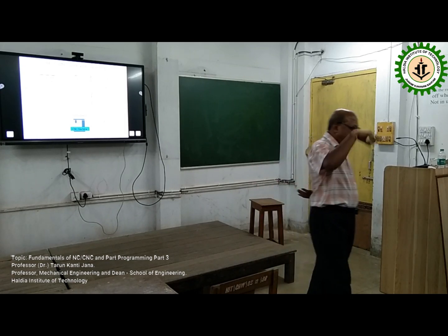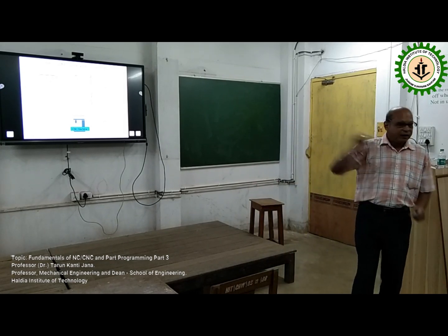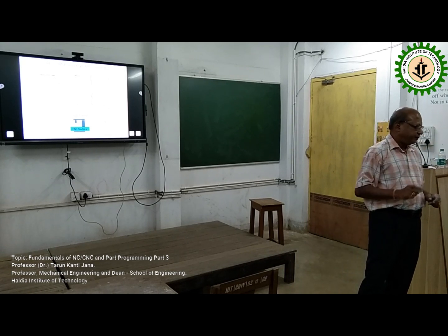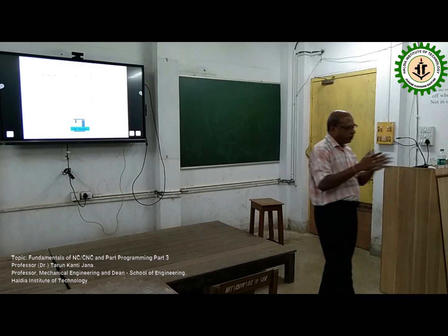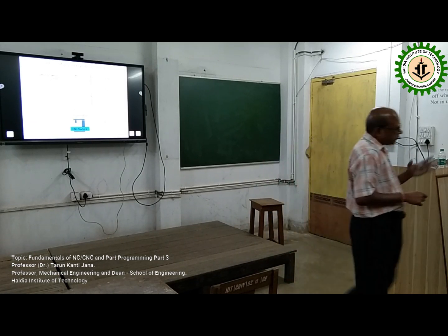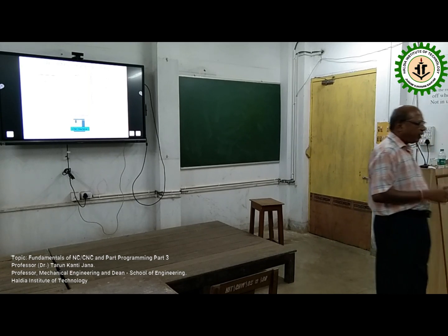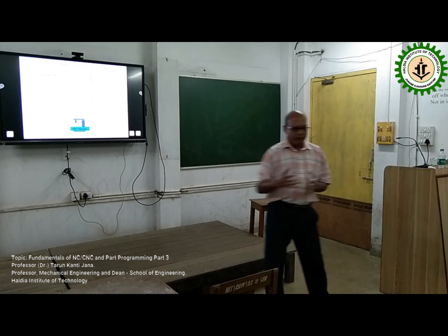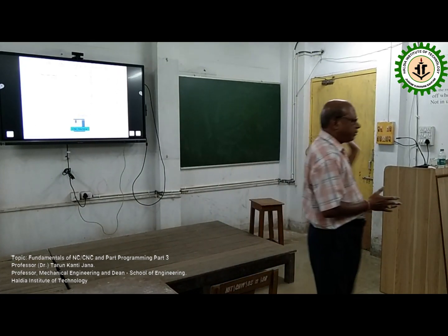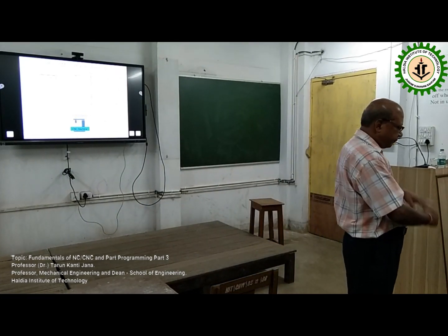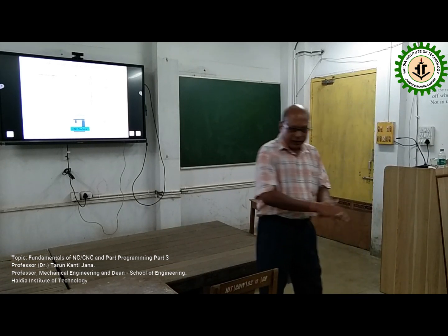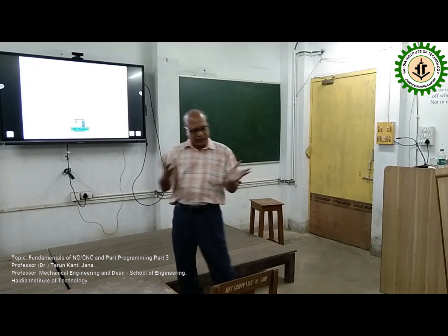If you wish the plunge depth in drilling to be 5 millimeter, your corresponding Q parameter will be 5000. Again, in the same block, for some other parameter you have to put 0.1, so 0.1 is in millimeter. For any of these, you need to consult the programming catalog provided by the machine. So this is in brief. Any other question?